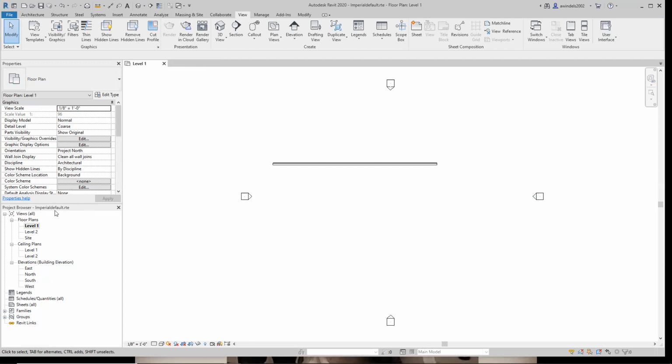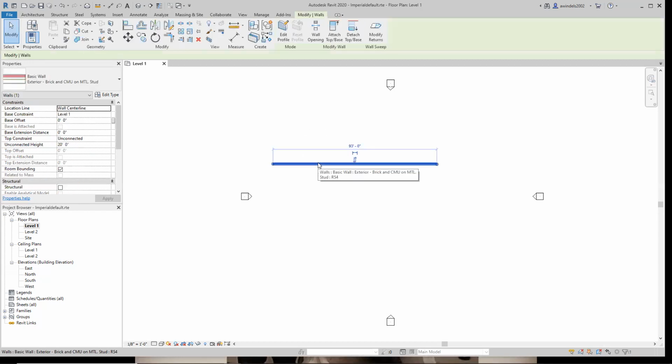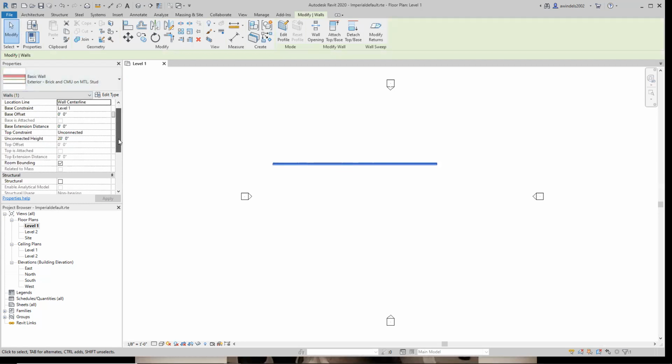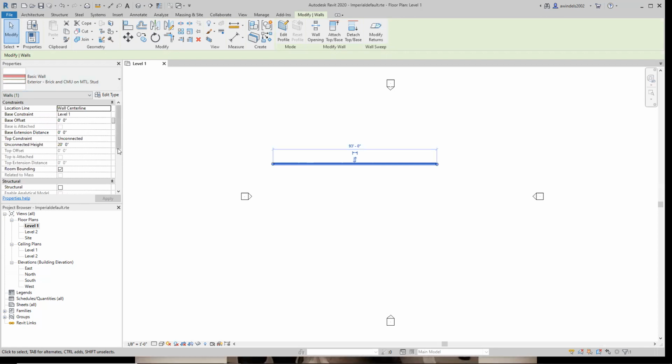Pretty critical things. We start chapter 7 and into chapters after, or excuse me, page 7 and page 8 into page 9. Properties box is much like AutoCAD. It stays open all the time. We're on level 1, but if you select a noun, this wall, basic wall, different properties come up. You can change things. This is going to be very critical to understand how and what this does. It's just the beginning here, but I often like to dock it to the left here on default. And you can pull a lot of these out. There's ways to lock your user interface, but I'm not going to do that now.